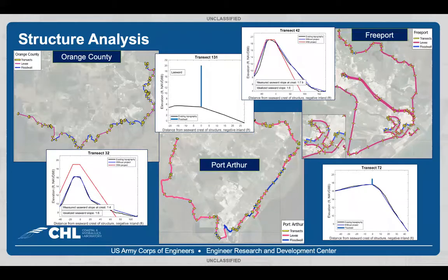The existing levee geometries did not have a nice linear slope, so we incorporated a slope analysis using the idealized without project geometries that weighted the slopes over a vertical distance corresponding to the storm water level, plus or minus 1 wave height for each of the probabilistic storms. The red lines on the levee plots represent the geometry of the feasibility authorized structure.